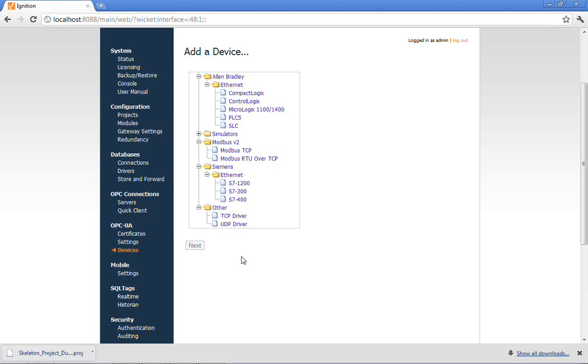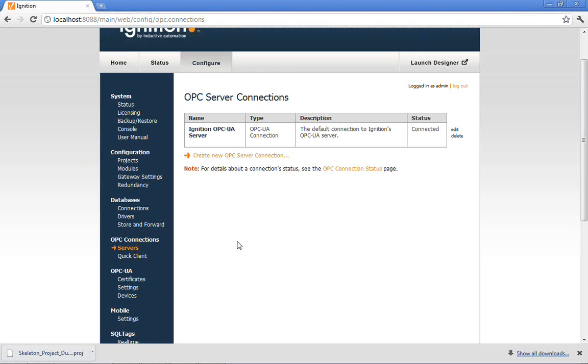So these are all the ones that are built into Ignition. However, Ignition is based on OPC, as many products are, where we can connect up to our own OPC UA server or other third-party applications like Kepware, Matrikon, RSLinx, etc. So if your customer has PLCs that aren't included in the base installed Ignition, you can still use other products to get connected up to those particular devices.